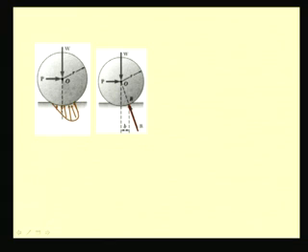So, we see that the resistance to rolling comes because of the moment of this reaction force R, which has to be balanced by an applied moment. So, if this force does not exist, then the wheel comes to a rest because of this resisting moment, the moment due to this force R.